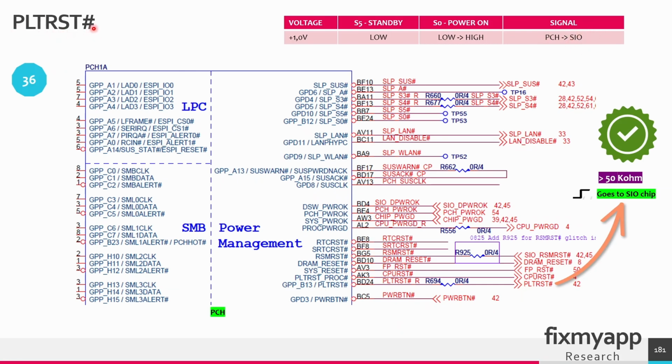The platform reset active low signal is the most important signal because it resets different components and circuits on the mainboard. When this platform reset active low signal is low, somewhere in the circuit there is a problem and it will prevent generating an enable signal or maybe some voltage. So then you have to troubleshoot which voltage in the sequence is missing.